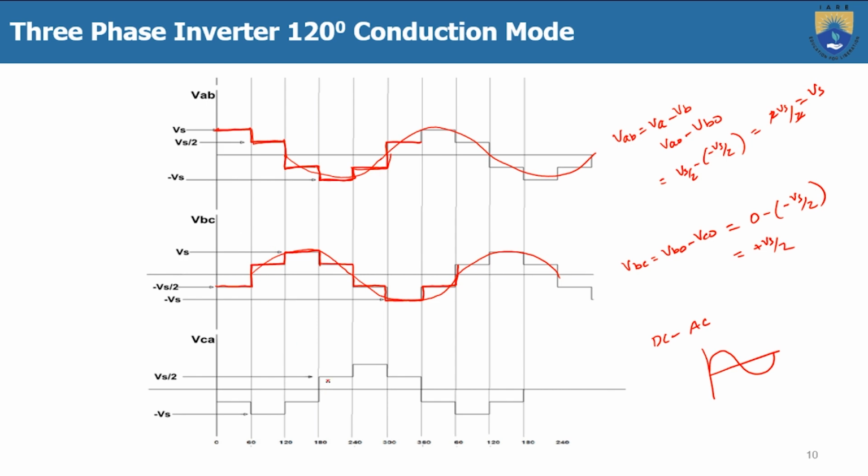Then how can we get this? Because whatever inverters we are discussing are usually 2-level inverters, because only 2 levels we are getting. One is either Vs or Vs by 2 and 0, and not even 0 here, directly from Vs by 2 to minus Vs by 2. So there are only 2 levels mostly. But there are 5 level, 7 level, 9 level and 11 level inverters.